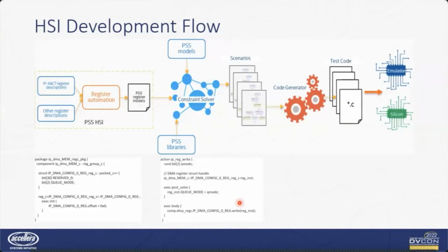You have write struct function which can be used to write a pack struct into memory, which we have used to write our DMA descriptors into memory. So with all these capabilities, you can basically write your driver code in HSI, and there is no need to write platform specific driver code like UVM sequences or C drivers. So this basically summarizes the hello world basics of writing your HSI sequence.